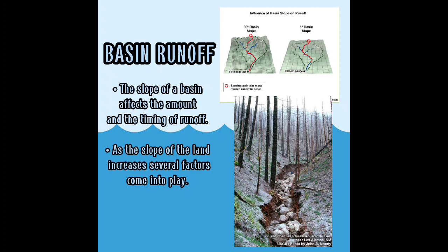With the land sloping, gravity no longer pulls the water directly into the ground, so more water is likely to become surface runoff. Another factor is the movement of water across the land surface. As the ground becomes increasingly steep, water will move faster and will have less time in contact with the ground surface, reducing the time during which it could infiltrate.